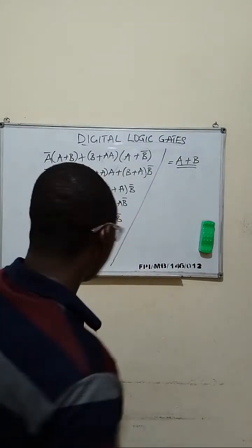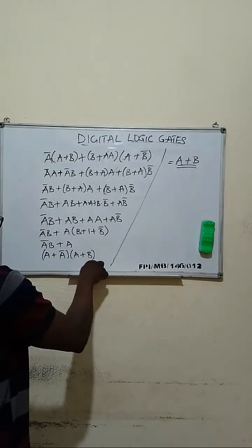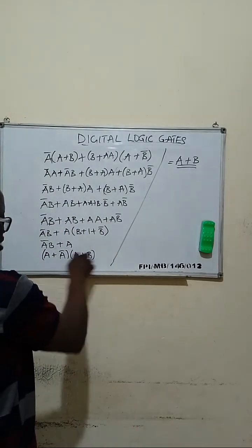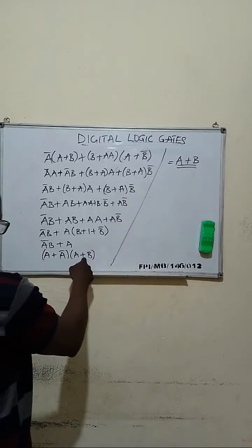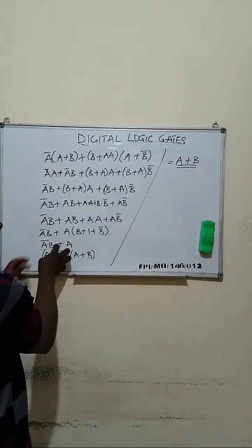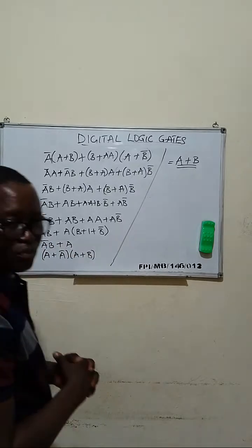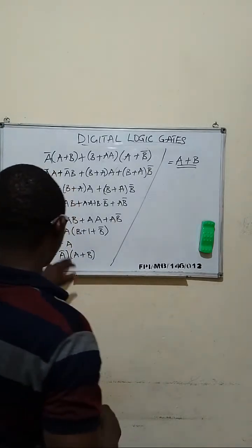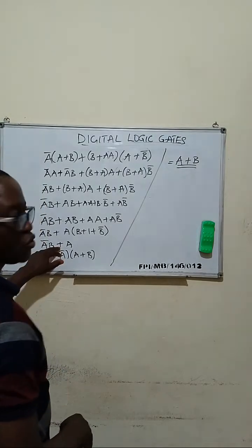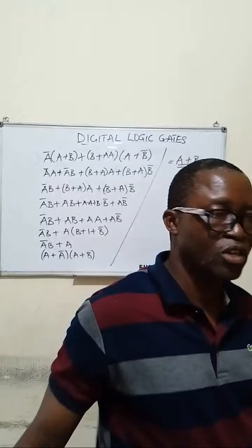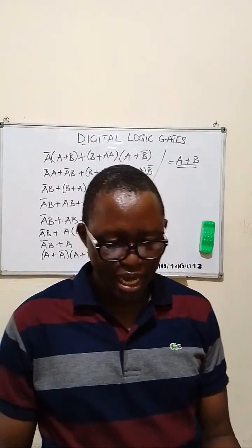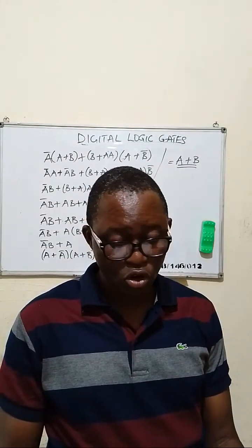When you finish, you go ahead and also implement this. Mark you, to implement this, you will need 3 gates. You have one NOT gate here, and 2-input AND gates that will take this one and this as inputs. So when you simplify, you're going to arrive at the same truth table as this. That is where the situation requires you to master the logic minimization laws.